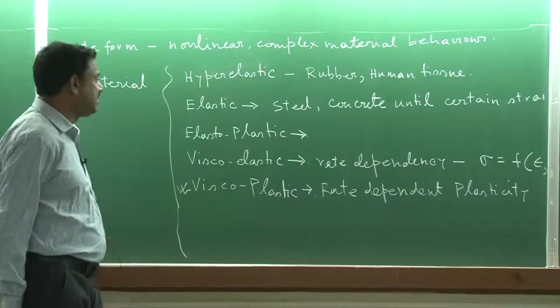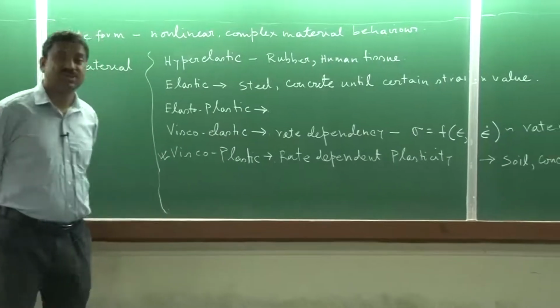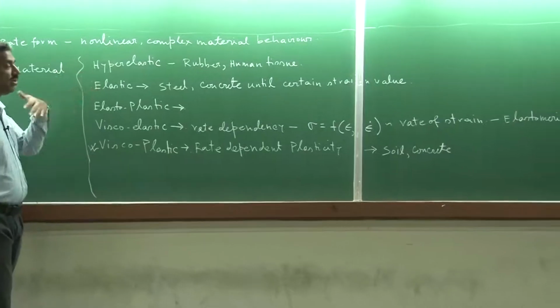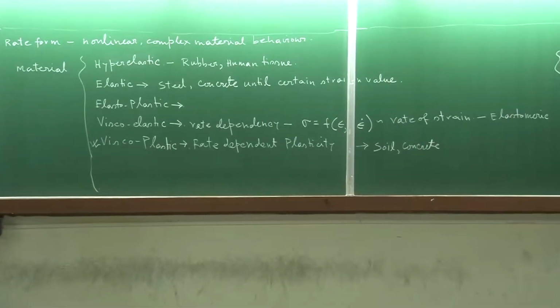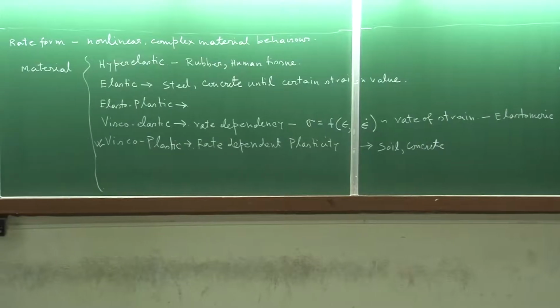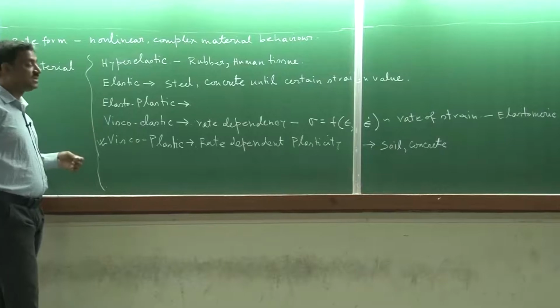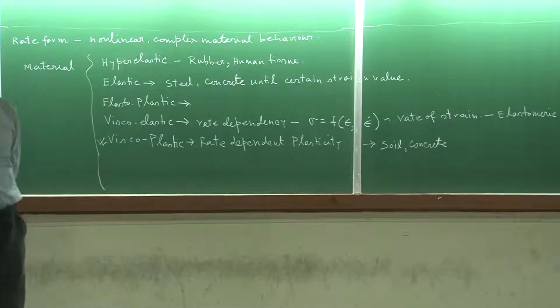Of course, things become much simpler when you do elastic than when you go to hyperelastic, because there the strains can be very large, so you need to consider finite deformation aspects. Objectivity and objective stress rate are all required in hyperelasticity, or even large deformation viscoplasticity and large deformation plasticity. But elastic is much simpler, because we are discussing the engineering strain with the Cauchy stress. Okay. So, we assume infinitely small deformation.